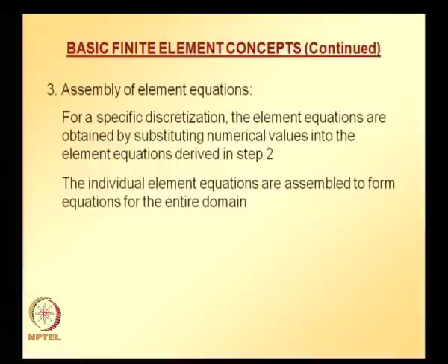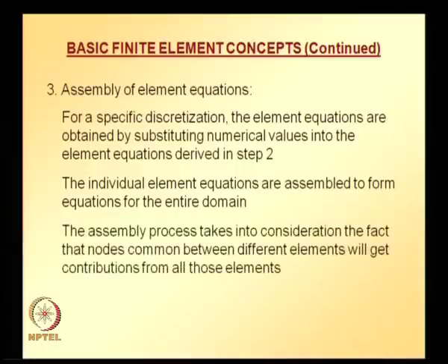Individual element equations are assembled to form equations for the entire solution domain. Okay? And this assembly process and other things will be clearer to you once we solve a problem in a while. The assembly process takes into consideration the fact that nodes common between different elements get contributions from all those elements.